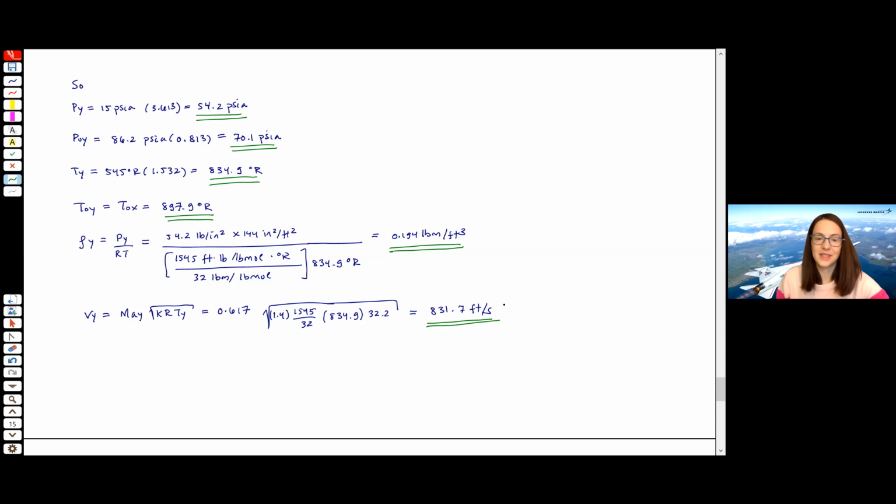All right, so that's the example. So it's basically going back and forth. If you've got quantities that you're trying to relate on one side of the shock, say stagnation to static pressure or temperature or density, you use table D.I. If you're trying to relate quantities across the shock, you use table D.S.